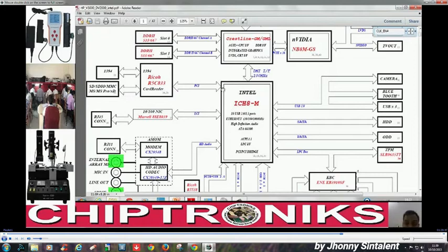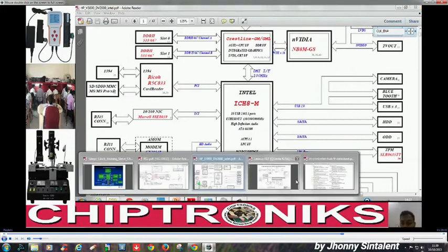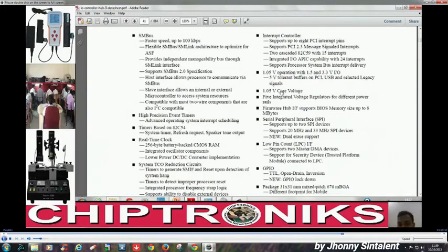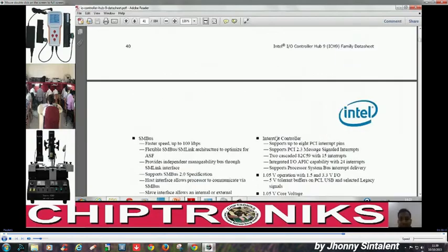The RTC section room is the first room. It is powered by 3.3 volt, right? And the core is at the center, which is powered at last, and the core section is powered by 1.05 volt. This is mentioned in the data sheet, and we are going to check it in the schematic also. So this is the way to look at the data sheet. This is the process that we use to study any data sheet of Intel.